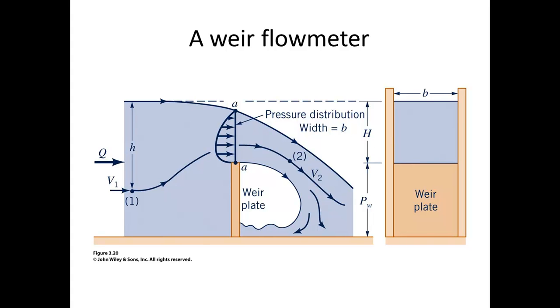Third option, a little more complicated. Let's suppose that for some reason you just can't get at the bottom of this fluid. One reason or another, it's not really accessible. What you can do now is, rather than open the plate at the bottom, open the plate at the top. And as before, you follow a streamline. Here's the Bernoulli application that you're seeing time and again. Here the streamline is the one from 1 to 2.